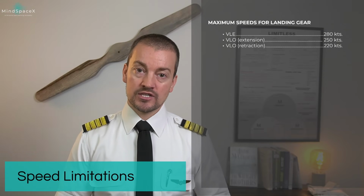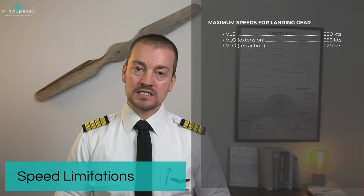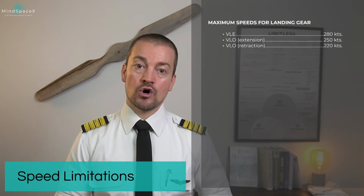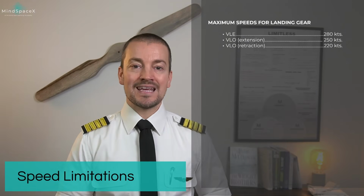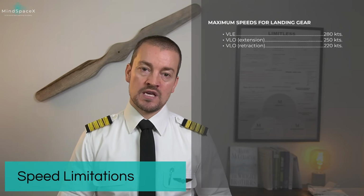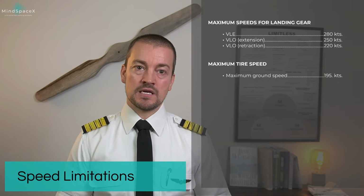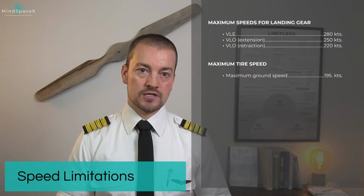VLO for retraction is limited to 220 knots. And this limitation is a lower speed because it places a limitation on the nose wheel, which has to retract forward into the nose of the aircraft, into the airflow. The maximum tire speed, maximum ground speed in this aircraft is 195 knots.